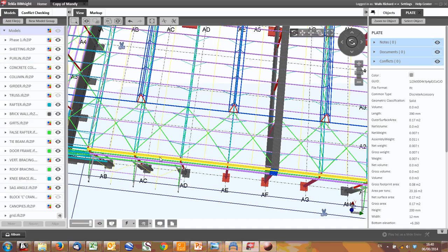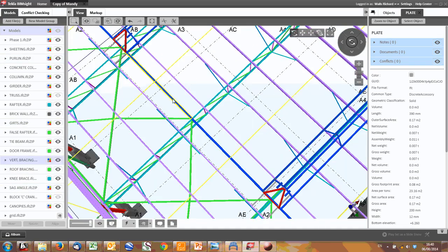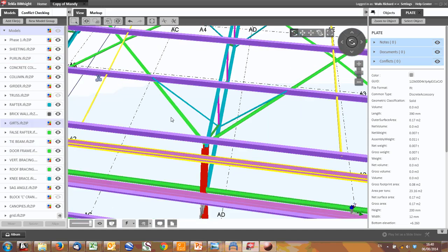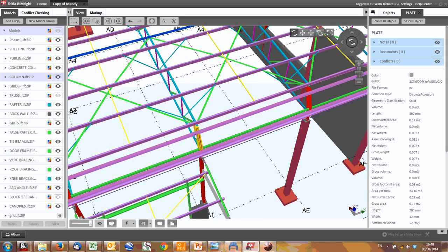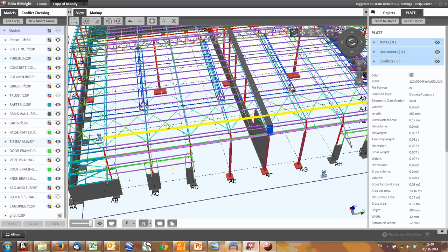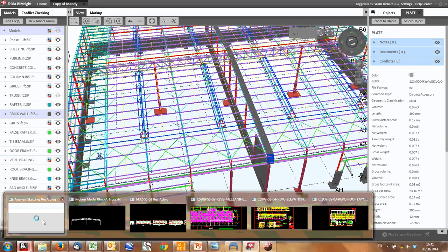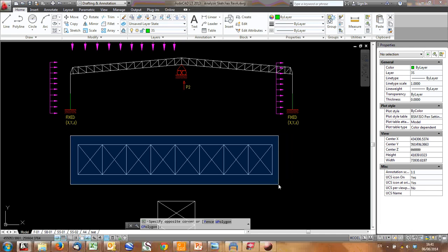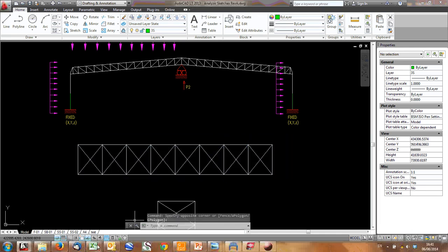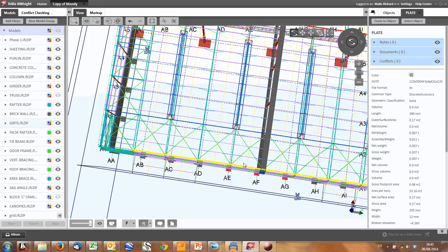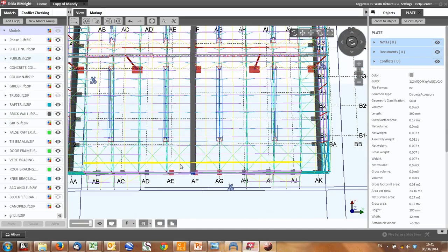However, to make sure this works, you've got to have something at the top, which is that blue pipe. There, and there's a pipe here somewhere. It should be, I think. And there's one there. And that then carries the horizontal loads, at the top and bottom. So I'm going to go back to our model. You can create a model that looks something like this. This is the roof bracing that we were looking at a few moments ago. Plan. There we go. There's our roof bracing.